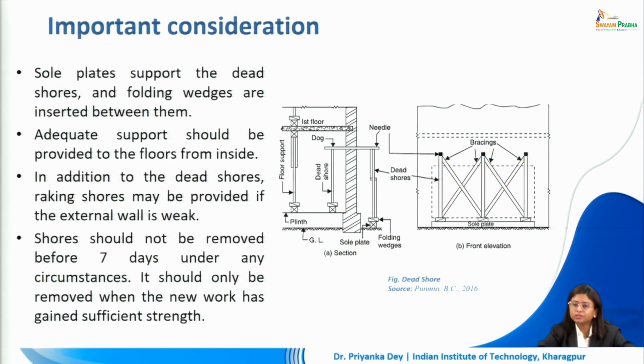Some important considerations that have to be made when dealing with dead shores include that the sole plate supports the dead shores and folding wedges are inserted between them. So if you see the figure here, there is a sole plate, which is this member resting on the ground, and the dead shore and the sole plate are connected with the help of the folding wedges. This allows us to secure it into position.